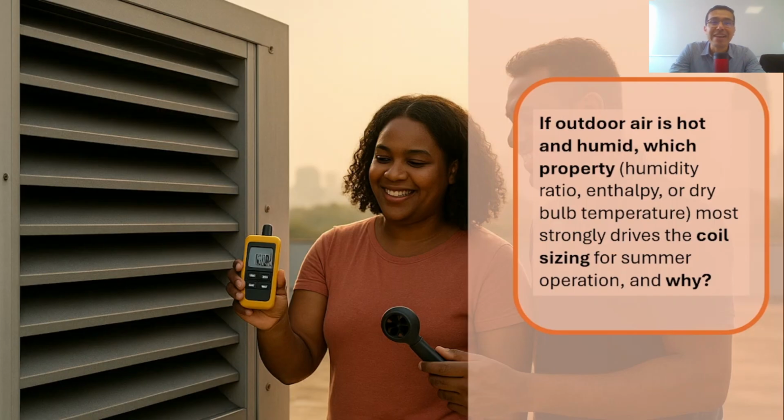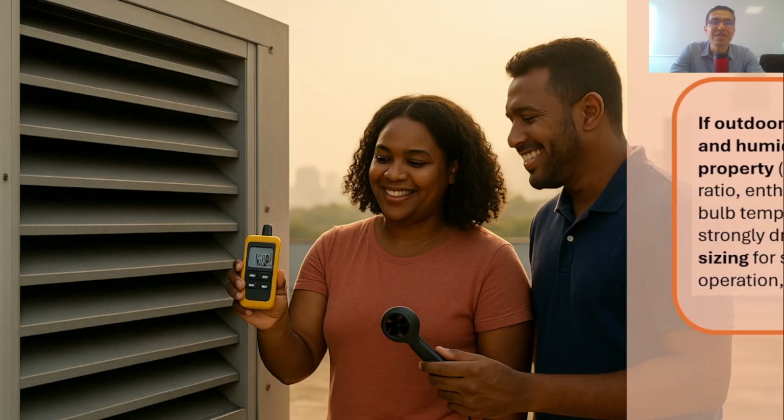Keep in mind that CAV and VAV share similar coil exit targets for dehumidification. So this means that the coil temperature in both systems is basically the same. But CAV may add reheat, while VAV reduces airflow. In both, if ventilation is significant, the latent part associated with humidity ratio can be the limiting factor.